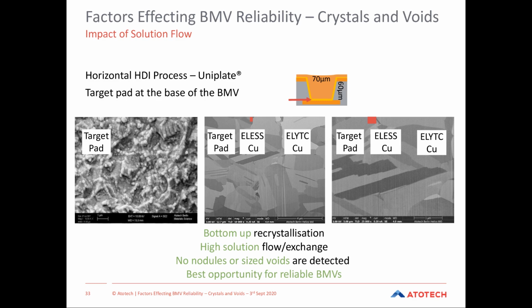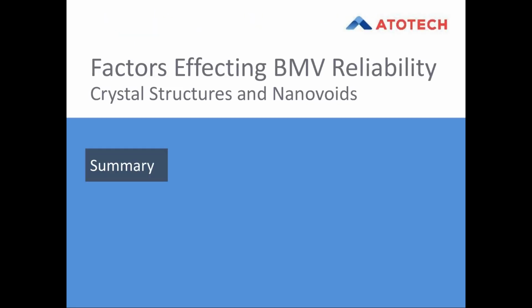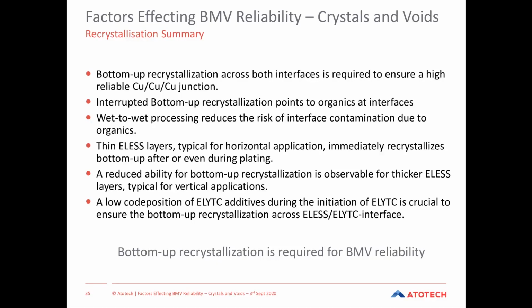Moving to a horizontal process, much as you would expect from a tech person, it's perfect. Typically we get very good crystallization. We get good solution delivery. We're not seeing a high level of voiding. And because of all of those, we're giving the best opportunity in terms of via reliability as well. So while I mentioned solution flow, we've now got enough data to say that actually it is important. It leads to mechanisms, and we can definitely see benefits from one versus the other.